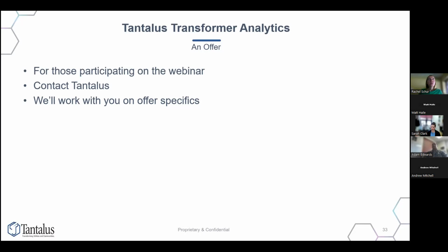Yeah, I think sometimes if we had an overloaded transformer that seemed like, oh, we've got 3 services off this one, and going out in the field verifying that, hey, this transformer is 10 kVA, it's not something bigger, there's no way all 3 of these could be on that, then that's kind of helped us track it down too. But I think if we had maybe 15 or 5-minute interval data coming from the meters, we could probably look at the profiles from that to see what all of them are seeing in terms of voltage and stuff like that. Then it would be really easy to tell which ones are off which transformer, but we mostly do our interval data, so it's not really granular enough to have something like that right off the cuff, I guess.